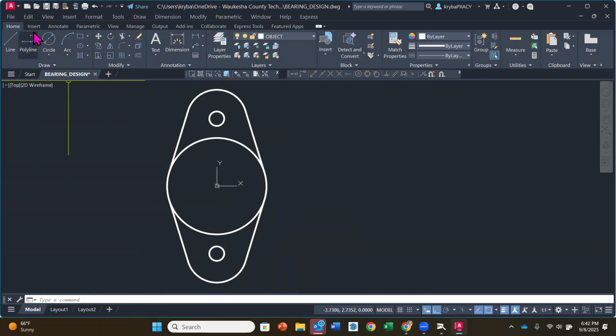Now to put the other one in, do the same thing: center, diameter. You can activate this circle to share the same center, or the half circle, because now there's this one here. So I'm going to click, and this one's going to be 0.625 for 5/8. And then I'm going to do that same thing, activate that center, 0.625 for that one. Okay, that's my top view. Questions there?